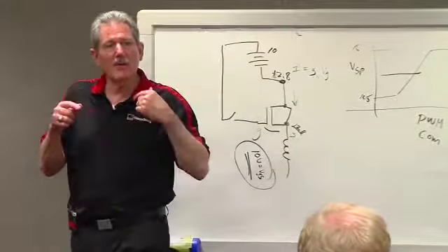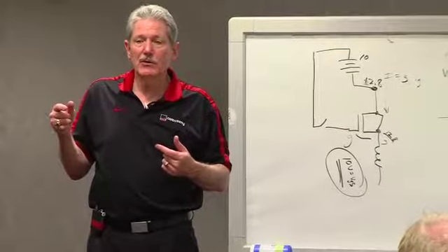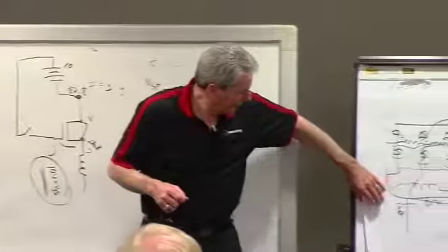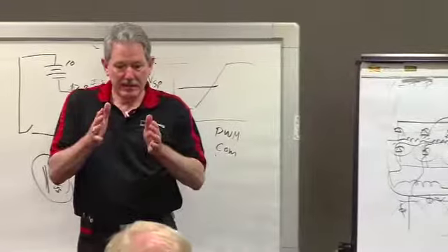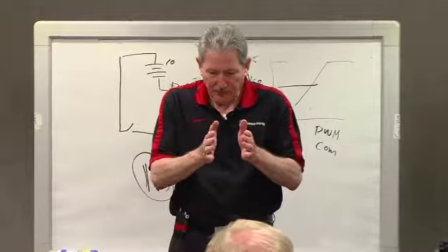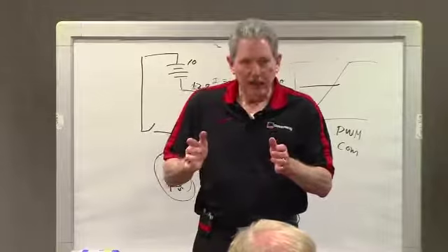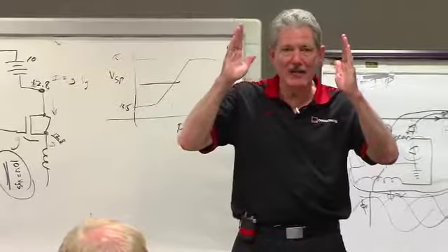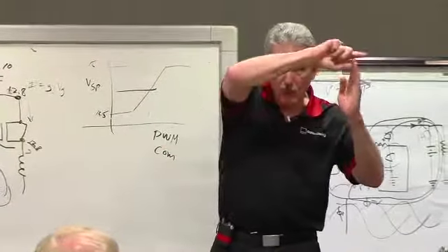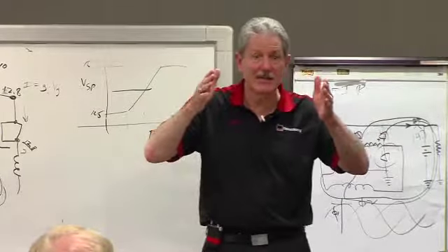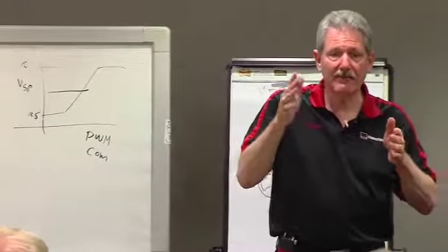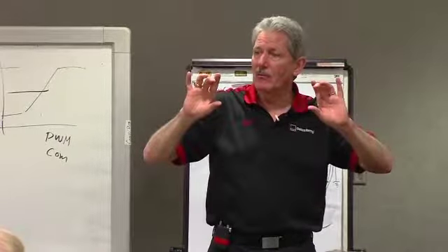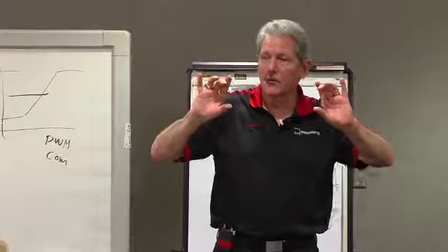There is another one behind that, and that is computer control using bit streams. Today, this is all PWM, ones and zeros, but it's duty cycle modulated. Here's full field, here's less. If we can now go ones and zeros, where I have a word, and that word might be 8 bits, so 111001, that now contains set point information. I want 14.75. I can also take another 8-bit byte and put in that load response control.